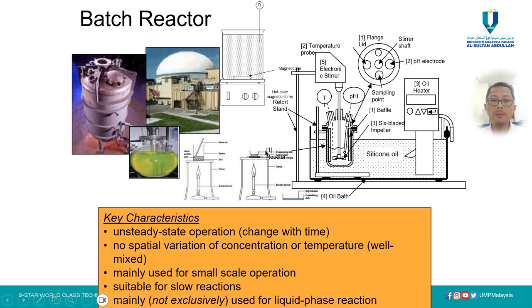Before we determine or calculate the mole balance, there are some assumptions made to simplify the calculation. First, for batch reactor, it is run under unsteady state operation, meaning we vary the time so that we can achieve the desired conversion. How much the reactant will be consumed depends on the time used to run the reaction.